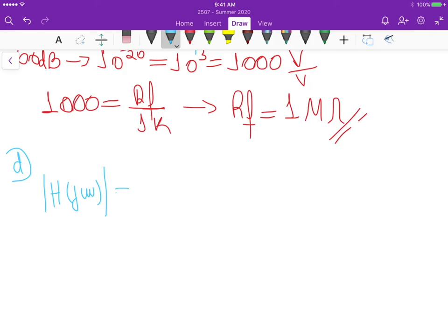Remember that for this particular case, sometimes you have to analyze whether it's an integrator, a differentiator, or what circuit you are analyzing. But in our case, we have a DC gain of 60 dB, and our 3 dB point is going to be the point where the 60 dB becomes 57 dB. So we decreased by 3 dB and reached 57 dB, right?